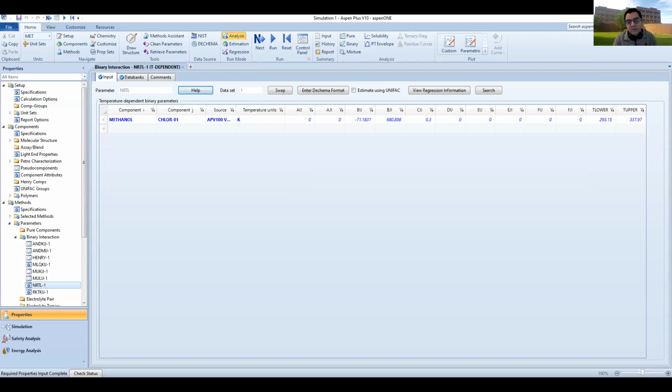However, what fugacity or an activity coefficient does is account for the chemical nature of these molecules, because all molecules have a chemical aspect, so you need to adjust for this when trying to calculate pressure from a molecular level. There's a refresher here that goes into Gibbs free energy and thermodynamics, and you can get very fancy if you want to, but for our cases, we just want to use it as a tool for Aspen.